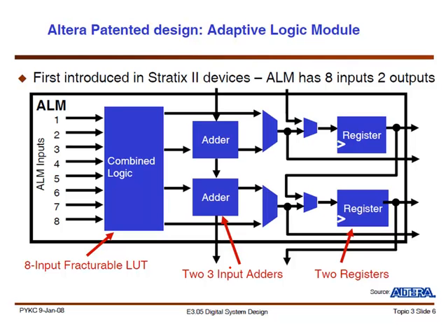And ALM is basically arithmetic and logic module, and this provides you the LUT, 8 input fracturable LUT. So you see the same story, right? I mean, you have an 8 LUT that could be broken into 6 LUTs or 7 LUTs and so on. And then you have fast adders here. You had a similar methodology, a similar structure in Xilinx. And then you have registers that you may or may not bypass, right? So you could use it for different reasons.